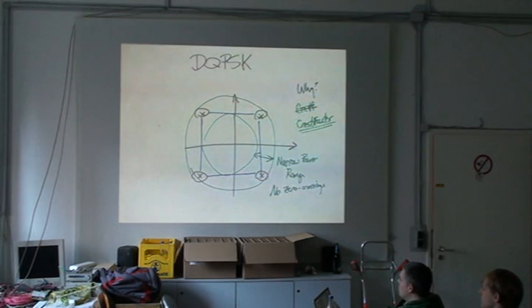So this is why you would do DQPSK. You're not transmitting any more information than BPSK. Your modulator is twice as complicated, but you've gained a lot of efficiency in your power by doing this.